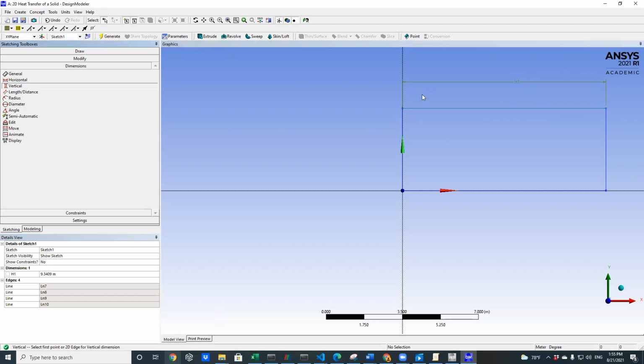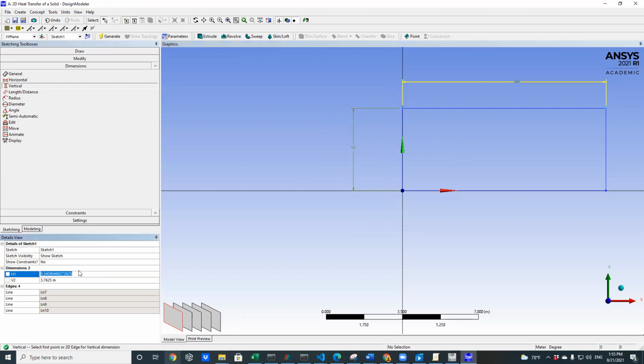So click on the point right at the bottom. Now Ctrl-click on your other point and drag. And that will give you your vertical dimension. So you see, there are these little tricks, but once we know them, it's easy. So now let's put our dimensions. Remember, we said that B will be equal to 5 and that the vertical dimension will be equal to 1.